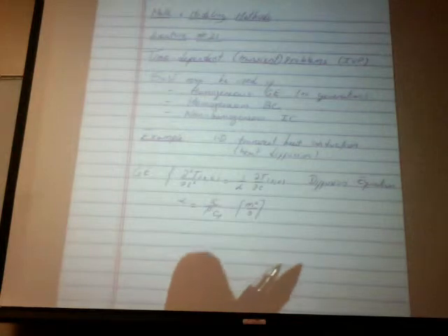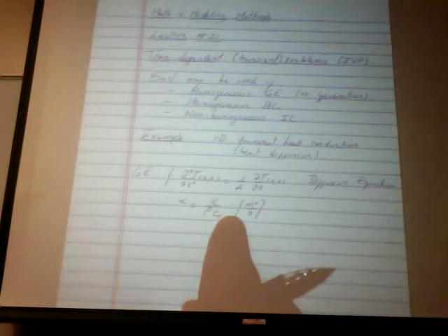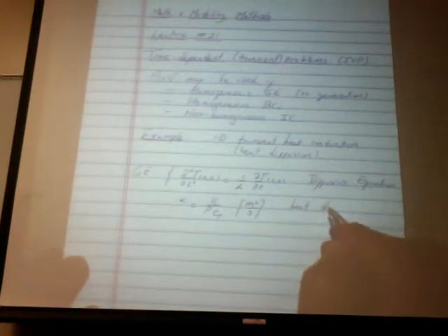This is the units of these. If you take the units of K, watts per meter Kelvin, the unit of density being kilograms per meter cubed, and the units of Cp being joule per kilogram Kelvin, you end up with meters squared per second. Any type of diffusion equation, whether it is energy diffusion in this case, or heat diffusion, or it is mass diffusion, or it's fluids diffusion, whatever it is, has a diffusion coefficient. This is called the thermal diffusion coefficient or heat diffusivity.